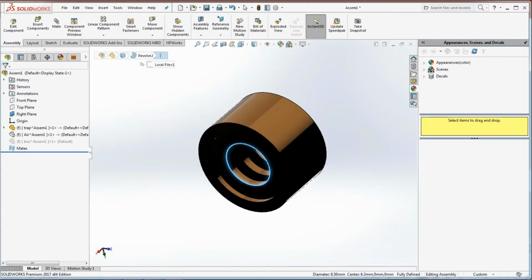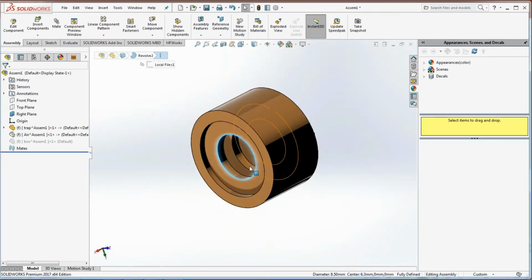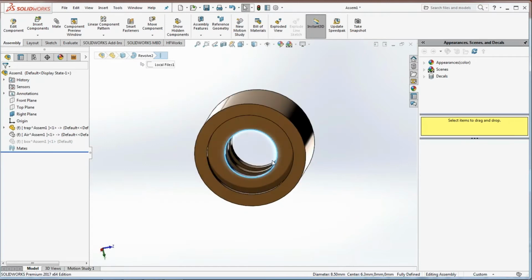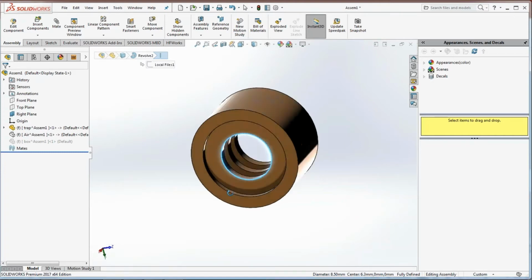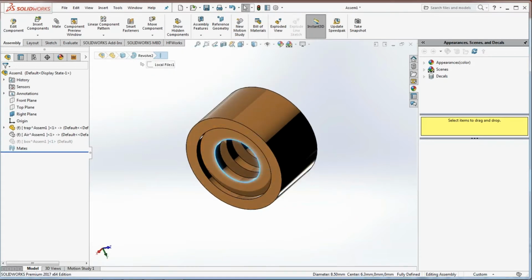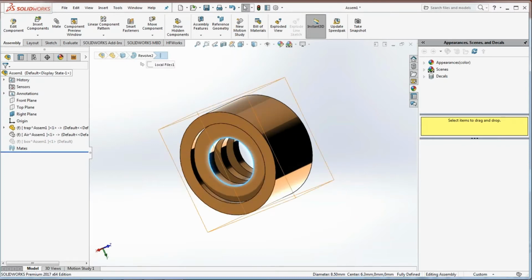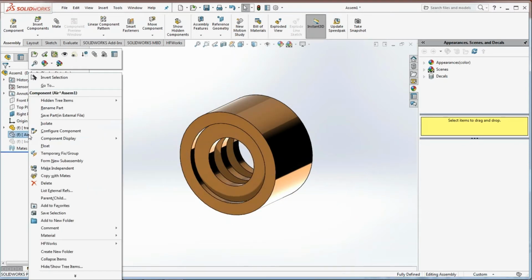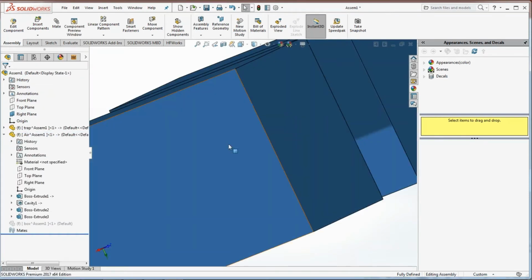So how to simulate it? Of course, when we're running a high frequency simulation using this finite element software, we need to mesh the path of the radiation. So how do we show the path of the radiation? The radiation is going through the air. So we need to create the air that the wave is passing through. In order to do that, I have created an air box. I'm going to show it now.